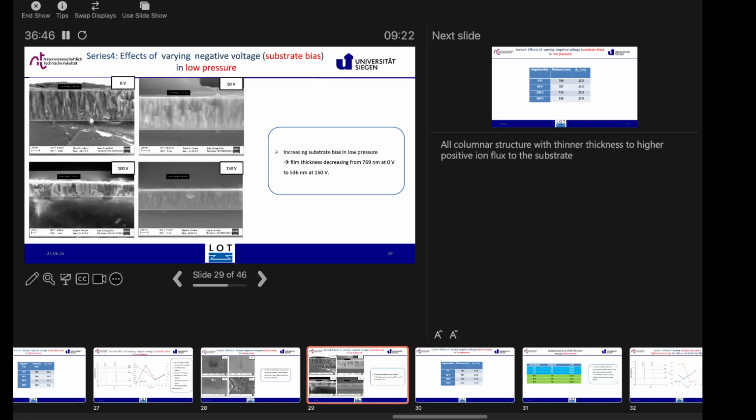In this case, why would you see a smooth surface at high pressures with high negative bias, without such effects of delamination or cracking of the film, but at low pressure you may observe such things? Like I mentioned before, I think at low pressure we got more resistance than at high pressure. That's why we got the delaminations.